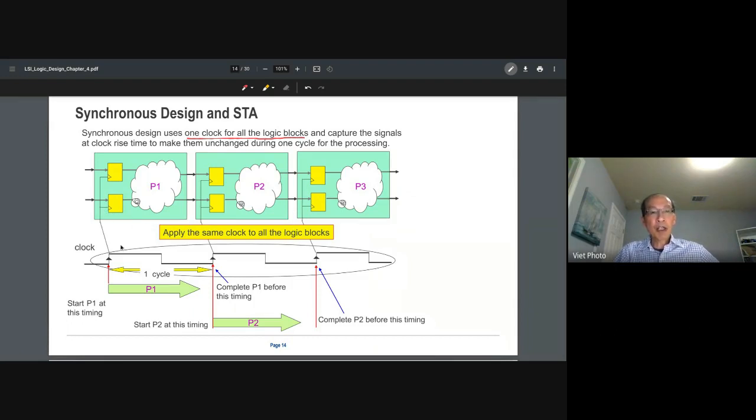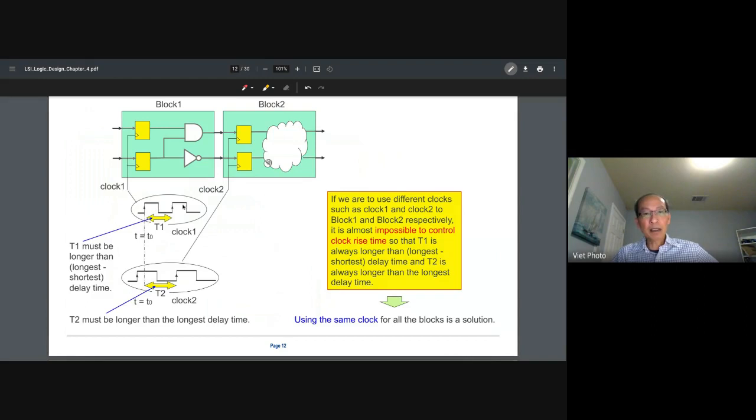So when you have one clock, everything just happens within the clock period. For P1, for P2, right? This one, when it happens here, is ready after a period, right before the next edge. So at the next edge, it will go to this one. The data here is ready and goes to this one, and the third one goes to this one. So this will solve any problem regarding the stable data or the asynchronous design here, because you don't know the phase.